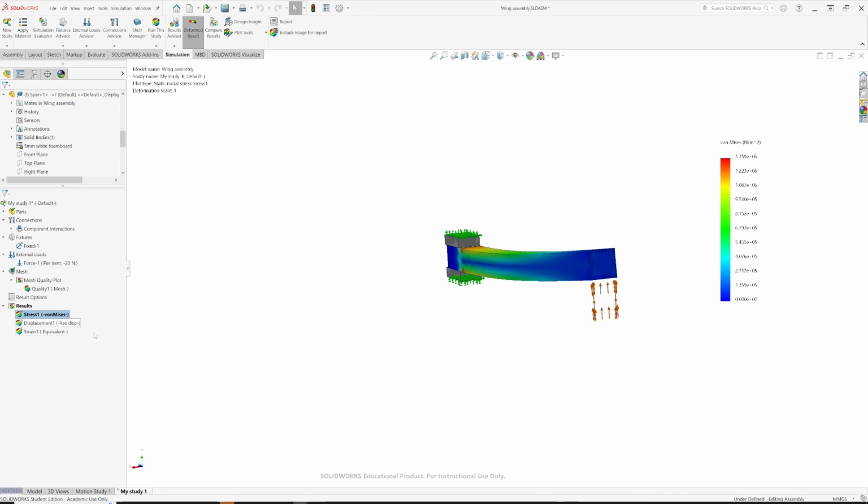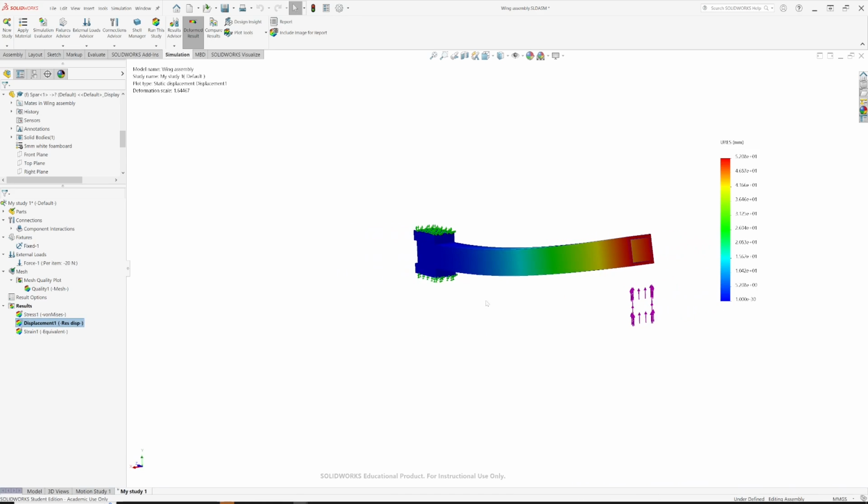And if we want to see how much that is, if we go to the displacement plot, you can see here it is deflecting, so this is now coloured by displacement, not stress, so it's not nearly as interesting as a stress plot, but the top bit here is displacing 5 times 10, so that's 50 millimeters.